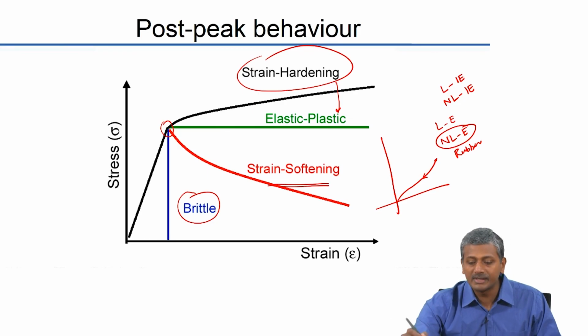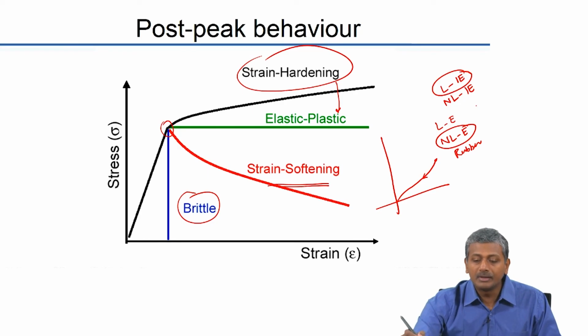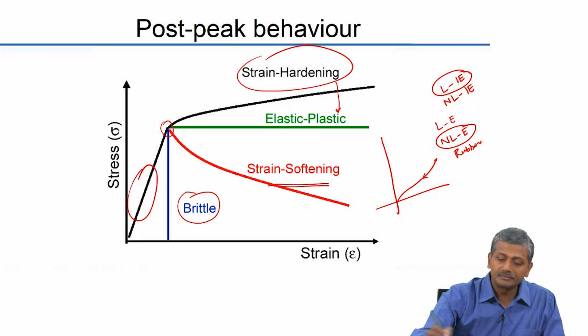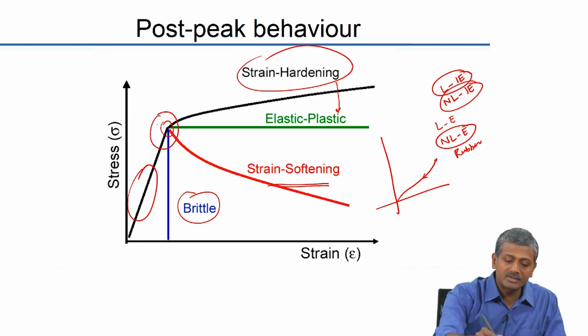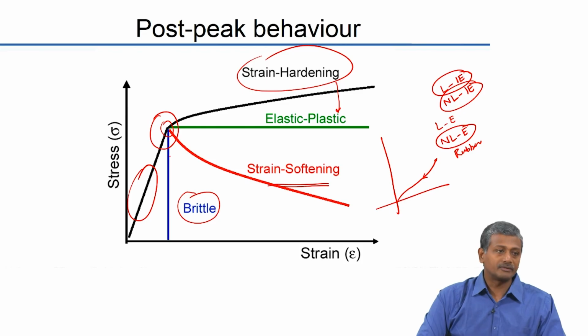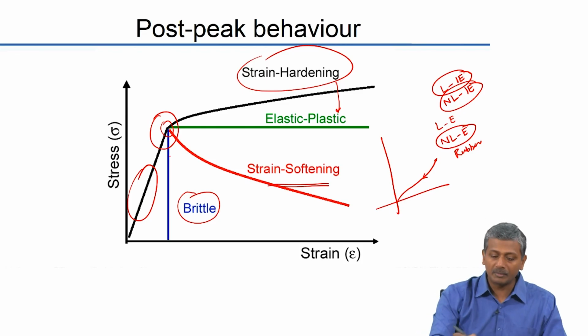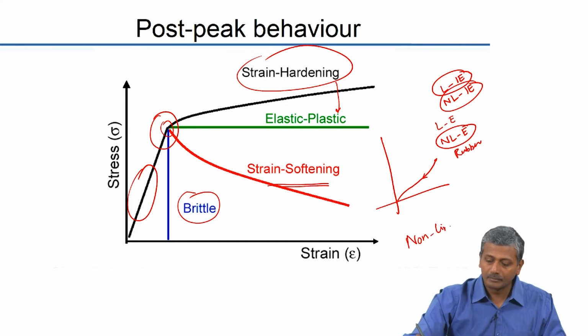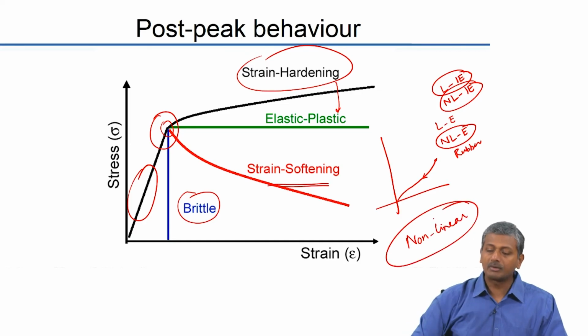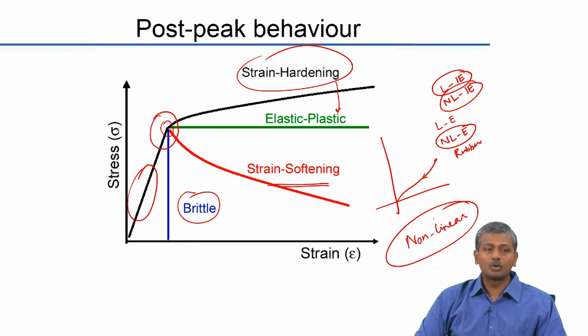So, concrete mostly is linear and inelastic in the beginning and non-linear and inelastic once it reaches the higher levels of stress. So, mostly we say that concrete behavior is non-linear. Concrete is mostly having a non-linear behavior, and as you strengthen it, you make it more and more homogeneous, increase the strength of the ITZ, and that causes the behavior of concrete to become more and more linear. Okay.